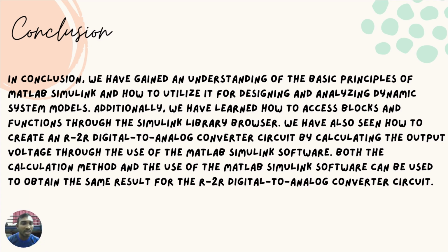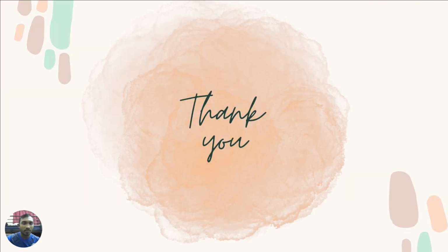We have also seen how to create an R-2R digital to analog converter circuit by calculating the output voltage using MATLAB Simulink. Both the calculation method and the use of MATLAB Simulink can be used to obtain the same result for the R-2R digital to analog converter circuit.